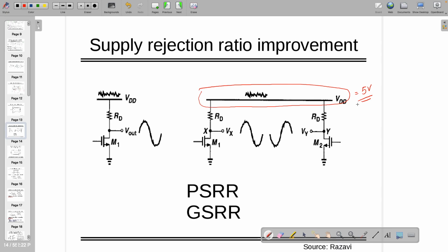So when you are doing the rectifier, what's going to happen? We will have some ripples. Then it will be filtered with the help of a capacitor. But still, it might not be possible to filter everything, right? That's why this signal is drawn over here like this. So this is the reality. If you are feeding VDD to an oscilloscope, you will see that VDD is not exactly stable.